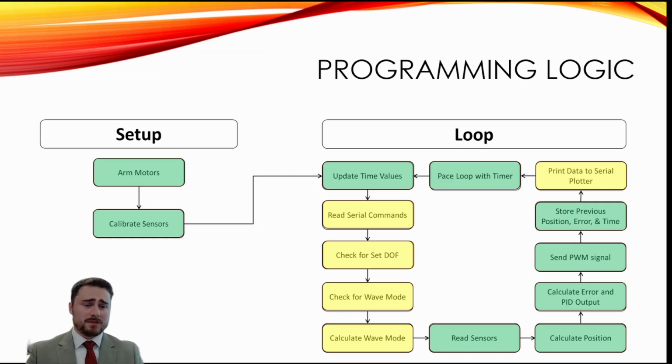And then it begins the super loop in which the timer begins. It starts by checking serial commands, and with the commands I can set different gain values, set which PID controller is active, and set different waveforms for the PID controllers to follow.